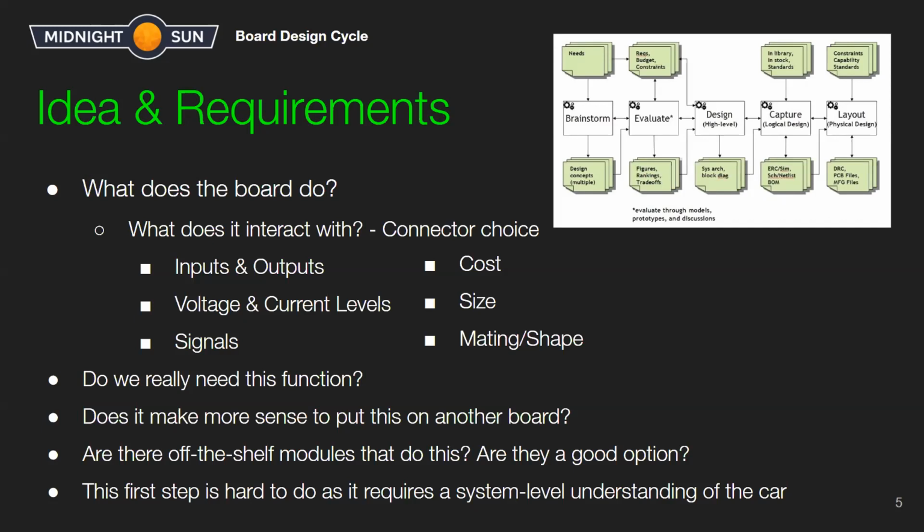Does it make sense to put this on another board? Fan control, for instance, do we need that on the DC-DC, or can we put it on power distribution? Are there off-the-shelf modules that do this, and do they fit our application? That can save us a lot of time and energy. You just purchase it, plug it in, test it, and make sure it does what it's advertised to do. And then we don't even have to go through any schematic, layout, or assembly ourselves. So that can be a huge time saver and cost saver as well.